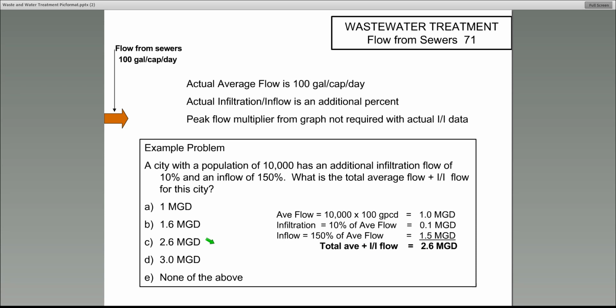If that's on the test, definitely work it, because you can work that in a few minutes. This is in your civil engineering book, and it gives you factors. It gives you things like for activated sludge processes, it's based on 1,200 gallons per day per square foot. So that's where I got the numbers from, this basic chart, this basic regulation.